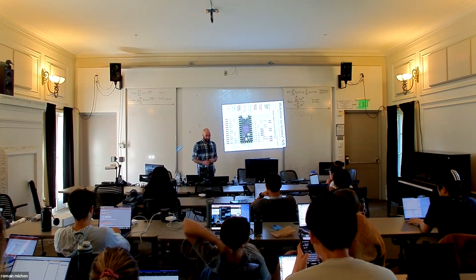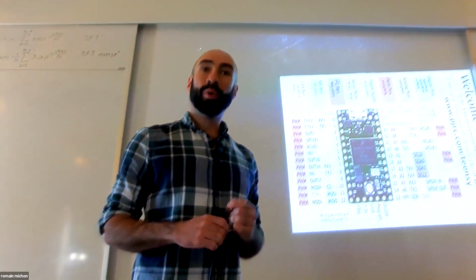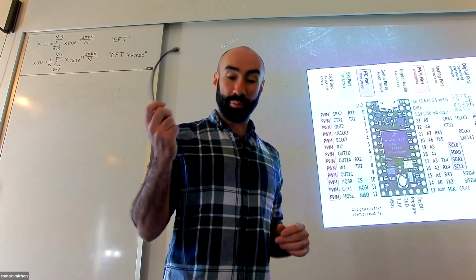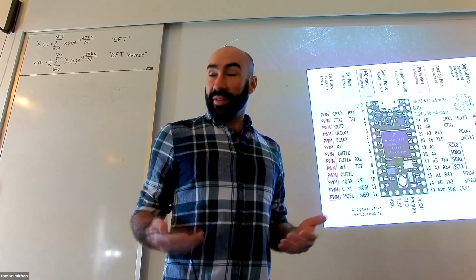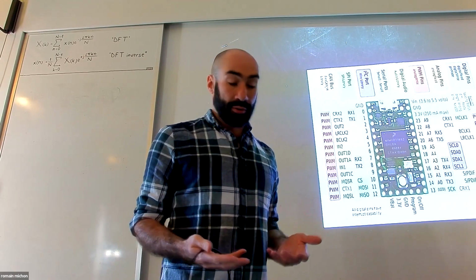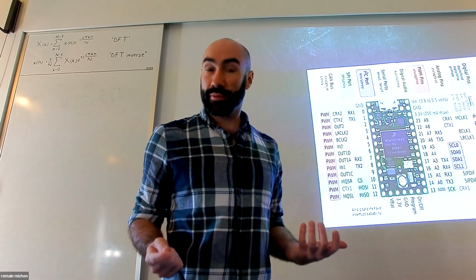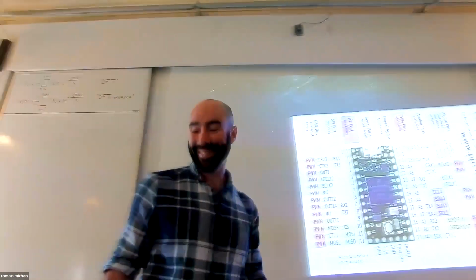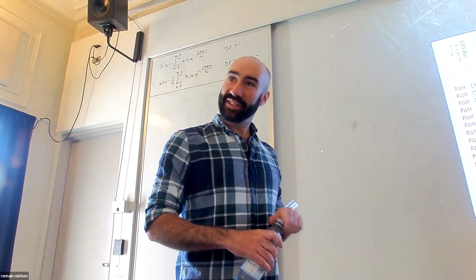All right, so there is an important rule, which is that whatever you do on the breadboard, you do it when the Teensy is not plugged into your computer. Because you know there is current in the Teensy. If you don't do the right thing, you could actually fry your circuit. You're probably not going to fry your computer. Probably. But you could fry the Teensy though.